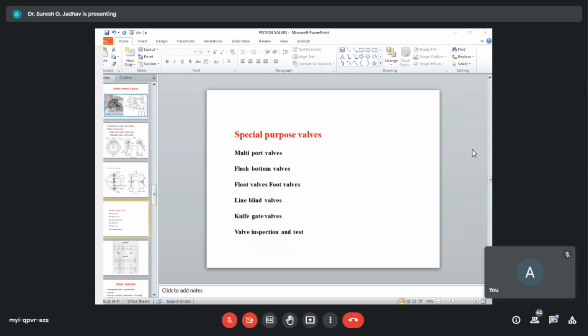The ability of the gate to slip through the plates effortlessly is the success of this design. The edge of this gate is set to shear the solids. An elastomer seal is used to keep the solids from entering the space between the plates when open, and to clean the sliding blade when it retracts.